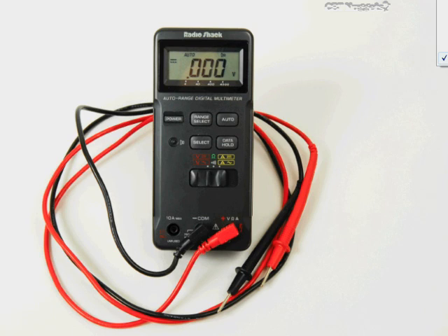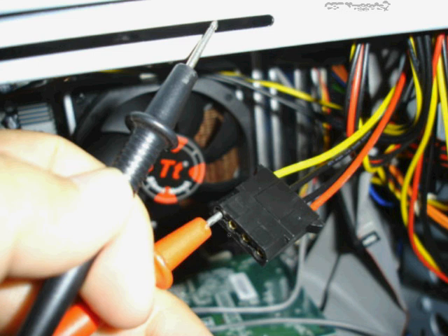An example of how I might use that is maybe I would be testing the 12 volt Molex connector, like I was right here. Here I've just put one of the probes into the 12 volt. This yellow line here is 12 volts. This red one is 5 volts. And these two black lines right here are both ground. Since I put the red probe in this yellow line, which is the 12 volts, then I grounded the other one,